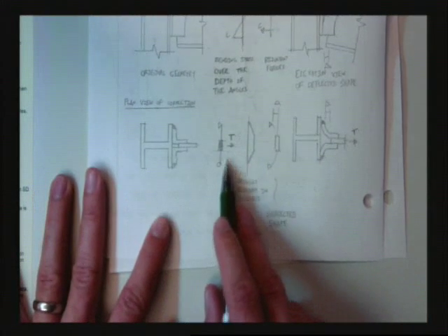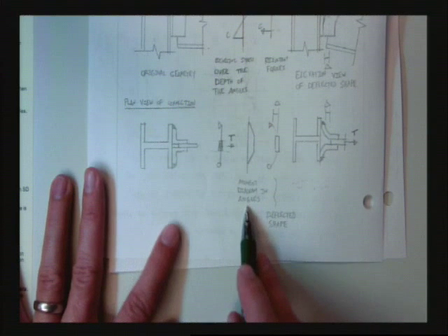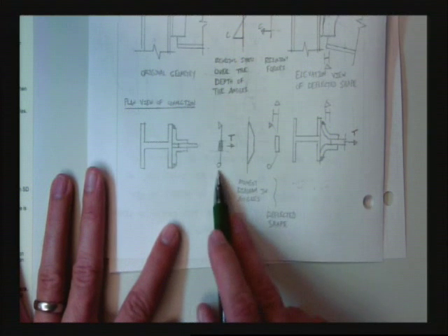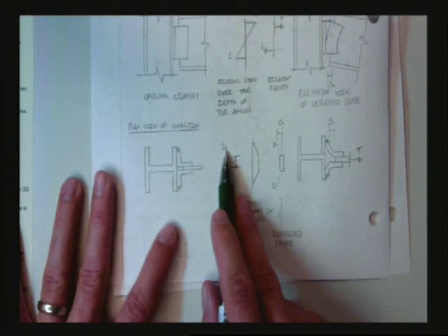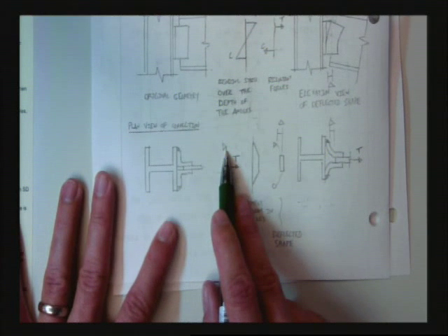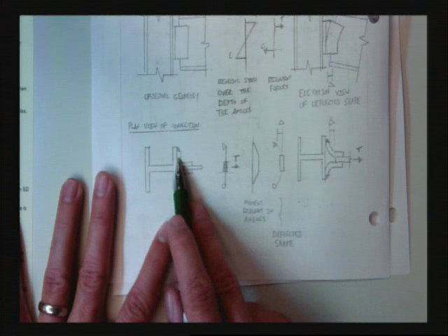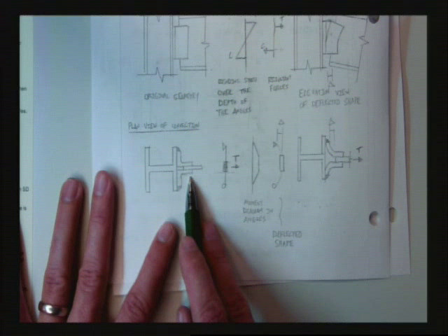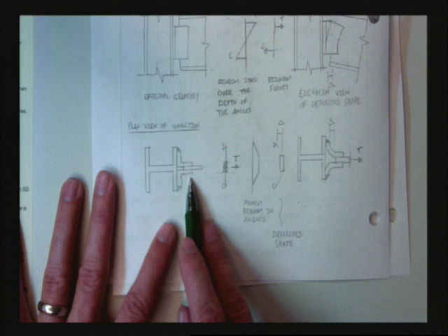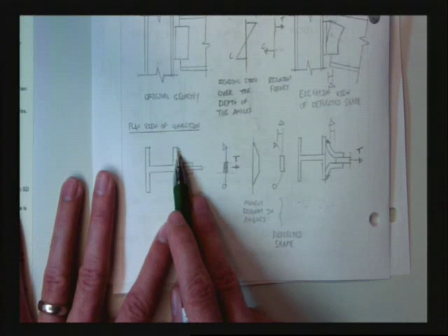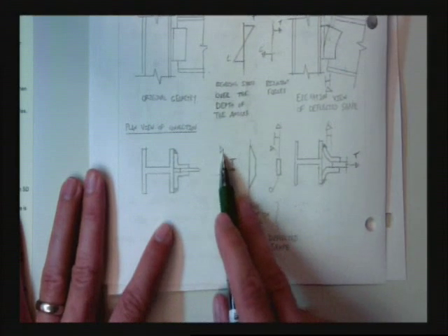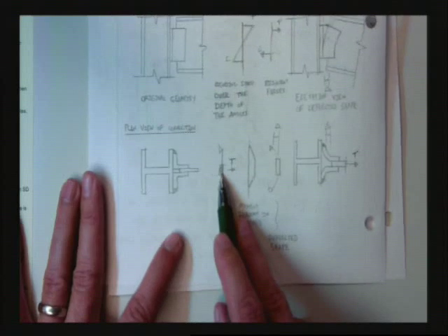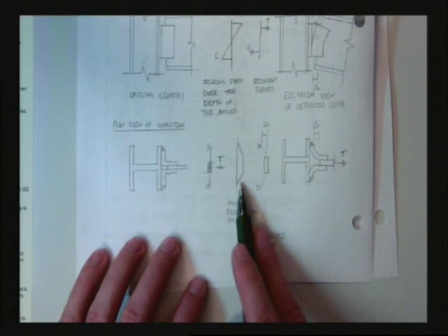So here's my plan view of my connection. Here's my simplified structure. There's my load on it. There's my moment diagram in the angles from a pin, because why are these pins? Because they're welds. But I have bolts here. They don't matter. What matters is here. We have welds, we have pins, we have this rigid area in the middle, we put this load on it, and we're going to get a moment diagram that looks something like that.